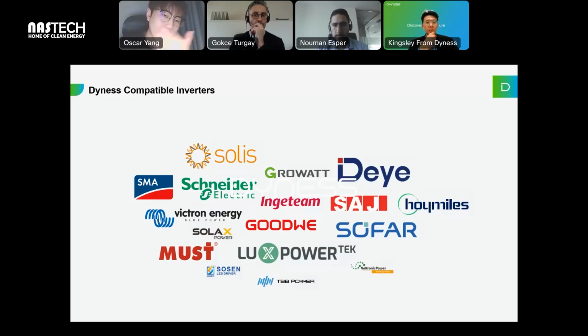So when you are buying Dyness, these brands of inverter can connect with Dyness. For other brands, for example Felicity, which I didn't show here, they support the Pylontech protocol, but we still don't have official testing yet. But in actual experience, we support the connection between the Dyness battery and the Felicity inverters.